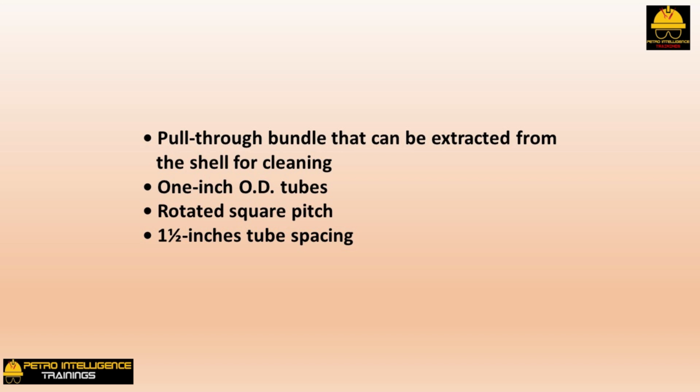The correct design, then, for this service is a pull-through bundle that can be extracted from the shell for cleaning. 1-inch outer diameter tubes. Rotated square pitch. 1.5 inches tube spacing. A 3/4 inch tube on 1.25 inch spacing, I would imagine, is also cleanable.